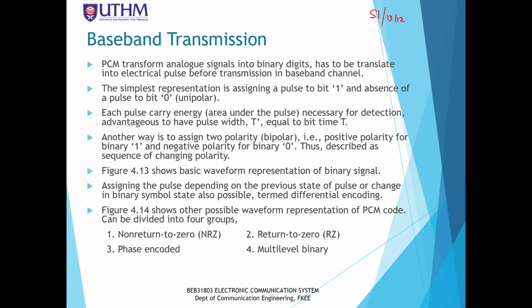The next slide is about baseband transmission. Baseband transmission is known as low frequency transmission, where we only use the same frequency as the input frequency. We are not converting the input frequency from low frequency into higher frequency. Normally for baseband transmission, we transmit the signal inside the wired medium.